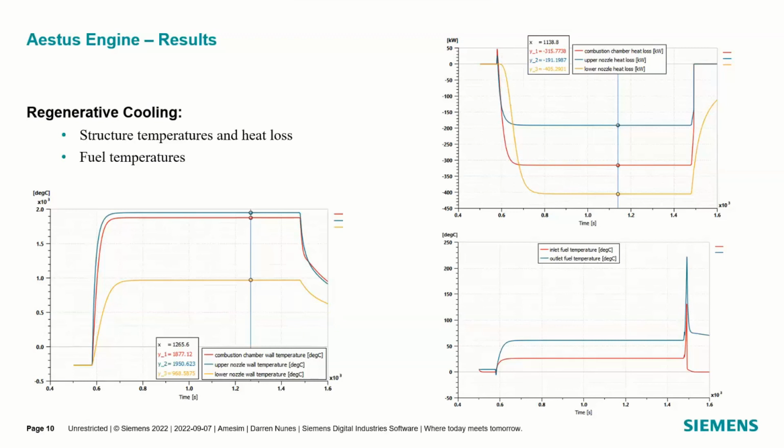altering or making this model higher fidelity, you'll see we add different tanks and we add different flow valves, and that's really allowing us to look at better transient capability. We know that, as you see here, when you are decreasing that flow, your fuel temperature ultimately increases exponentially, right, or sharply.